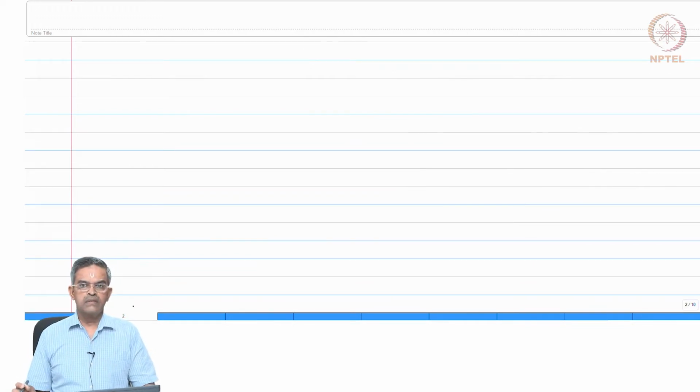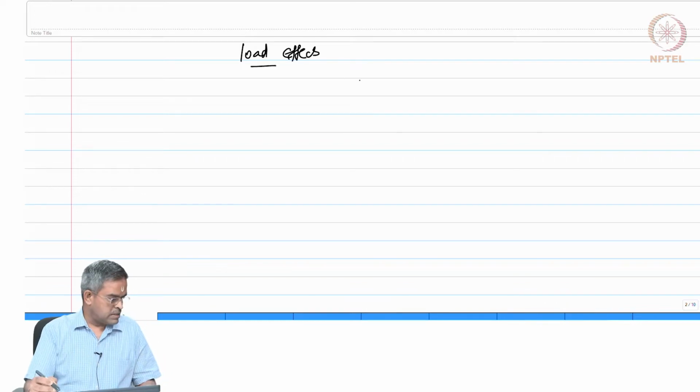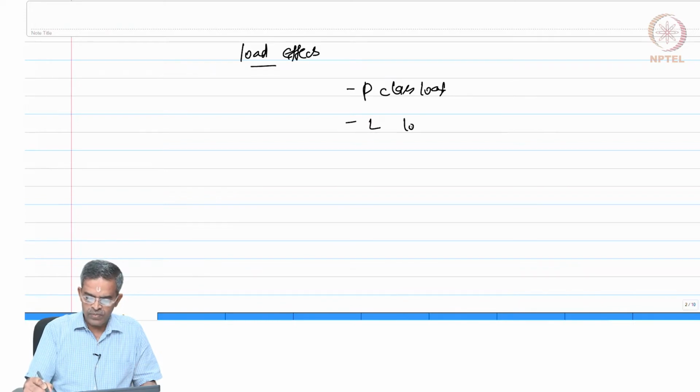So, in the last lecture we summarized that there are different classes of loads which are classified based on load effects, and they are classified as P class load, L class load, deformation load, environmental load and accidental load.